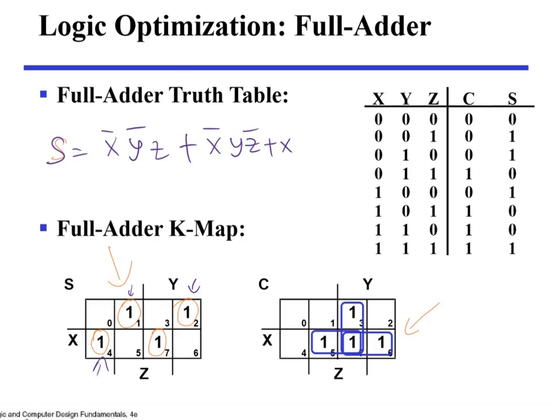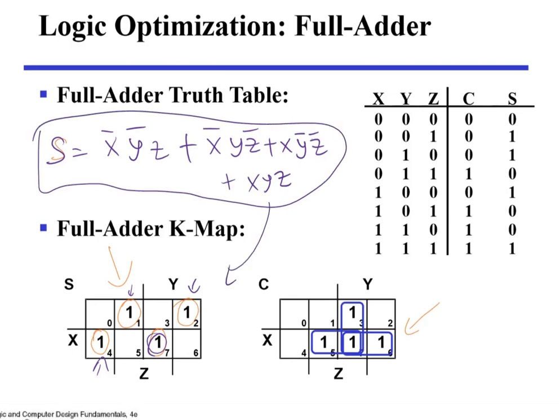X, right, Y naught, and then Z naught. And we have the last one, which will be equal to X, Y, Z, right? This is the Boolean expression for the full adder, and we can see that this is a 3-bit exclusive OR function, right, which can be simply written in compact as X exclusive OR operator, Y, and then exclusive OR operator, and then we have Z.